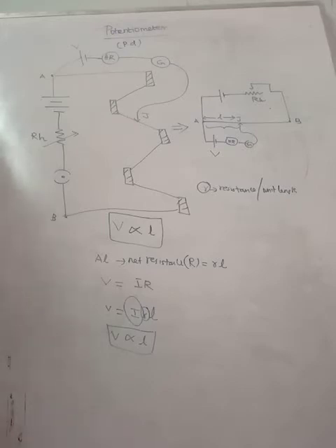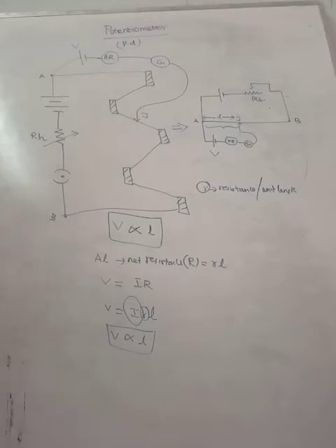What is the meaning of that? If the temperature increases, the resistance of the conductor will not vary. That means the variation produced across the given conductor will be negligible. That is the reason the manganin wire is used. So these are important points, the principle of the potentiometer.